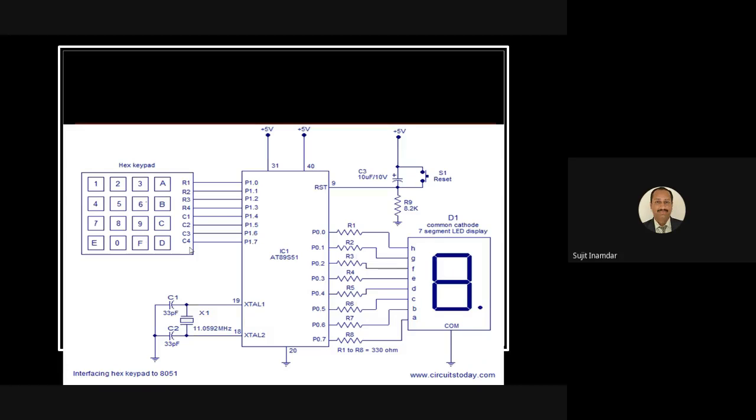That means 1111 and after that 0000. So the instruction, with a little modification, will be MOV P1, #0F0H. That will be the correct instruction. A little modification she has tried. Very good, madam. That means you got the logic, but we should also remember the MSB, LSB concept while making such instructions.